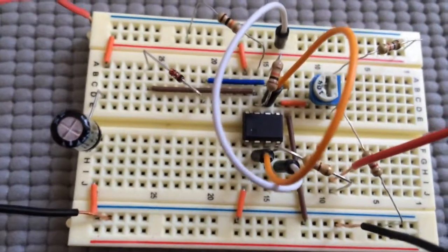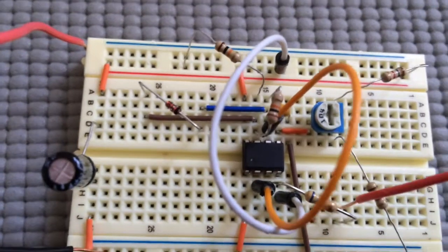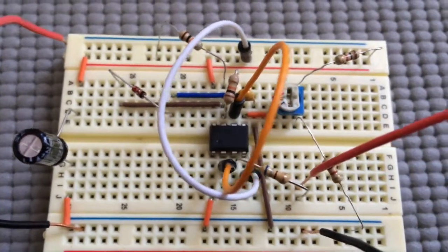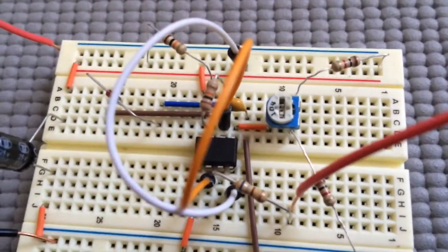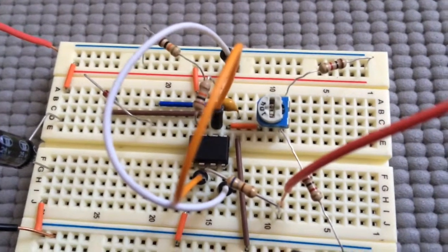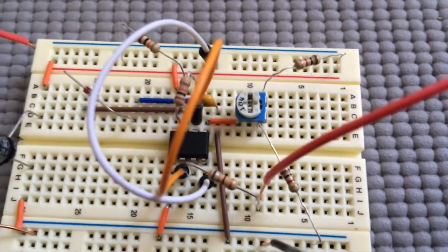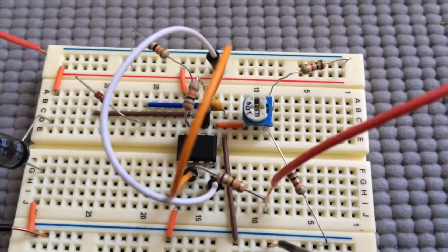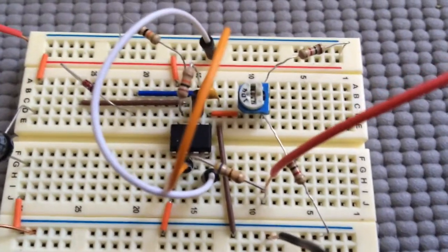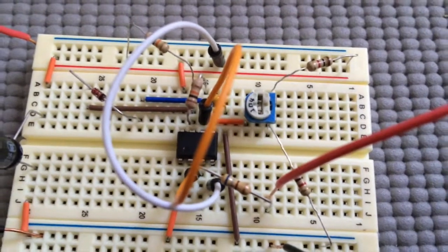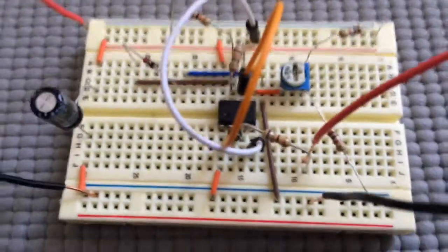So let me get a few shots to show how things are wired up. It's pretty much the standard astable 555 chip configuration, with the only change being that the threshold pin, instead of being grounded through a capacitor, now runs through a trim pot, which is grounded and powered by 2 resistors to be sure that there's always a resistance across ground and power. As the trim pot is varied, the threshold will change for cutoff.